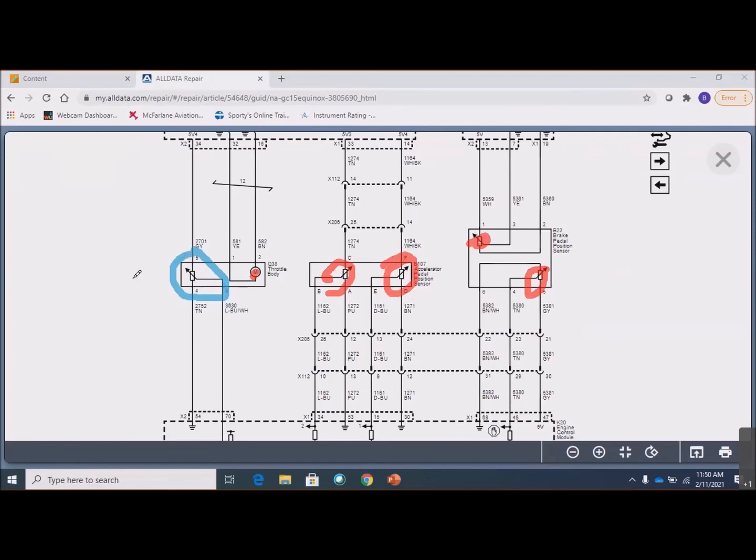And that throttle position sensor is basically the other end of the wire from the accelerator pedal, right? So the accelerator pedal position sensor is telling the computer what the driver wants. The computer is then using the throttle body, this electric motor, to move the throttle plate based on driver demand and things like that, and then looking at the throttle position sensor to see where the throttle plate is at and to make sure that it is following the commands of the throttle body.